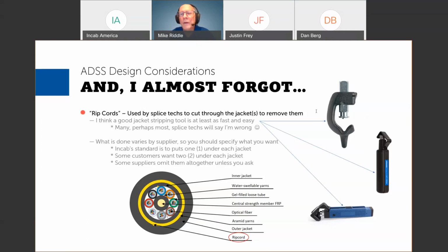And do both of the jackets have the same tracking characteristics, talking about the double jacket cable, obviously? Yes. I mean, the polyethylene is the polyethylene, and you're going to get the same performance. If you're making a track resistant cable, though, you only need the tracking resistant material on the outside of the cable. The way the tracking mechanism actually works is such that it doesn't get to the inner jacket.